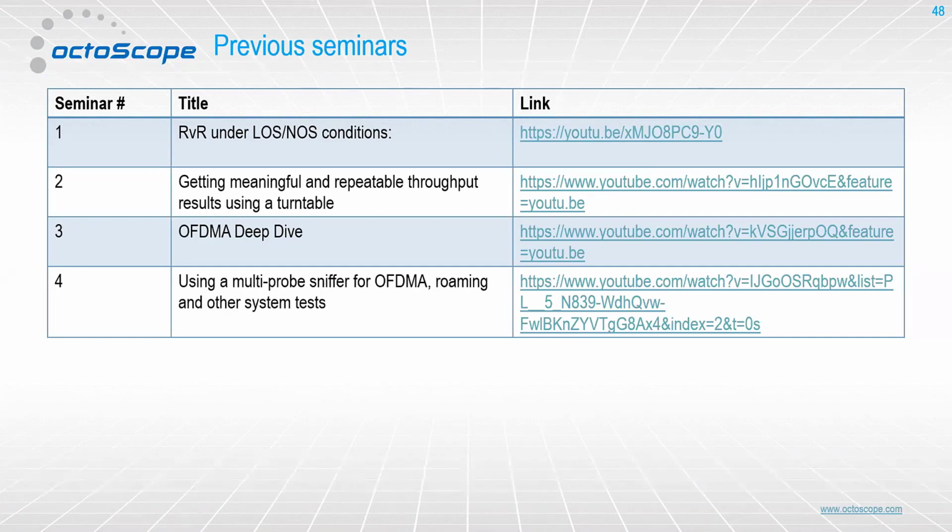Okay, so just to be really clear, path loss doesn't change based on regulatory stuff. The link budget changes because the transmit power changes, right? Path loss is a component of the link budget, and that's based on physics. The transmit power is based on regulation. So how can you control that? Well, the test bed itself doesn't particularly care.